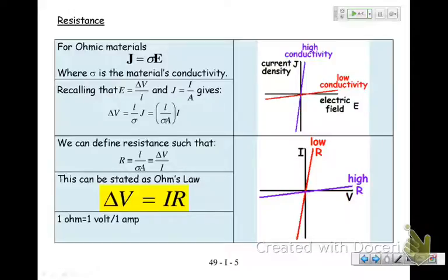And you're going to use Ohm's law over and over again, which says that the EMF, or the potential difference, if it's the power source, it's called an EMF. If it is the effect of that power source across that component, it's called the potential difference. And you can think of it as water pressure and water flowing through. That's a good analogy. But the potential difference is equal to the current flowing through that component times the resistance of that component. So V equals IR.